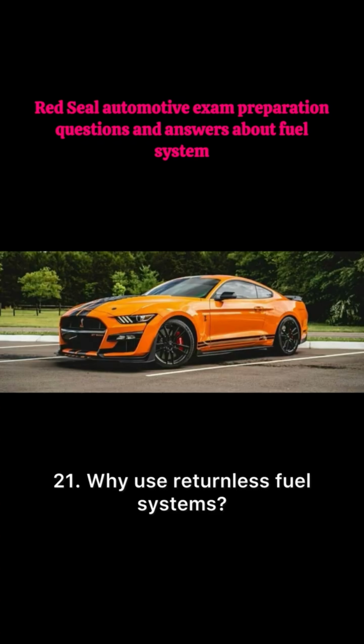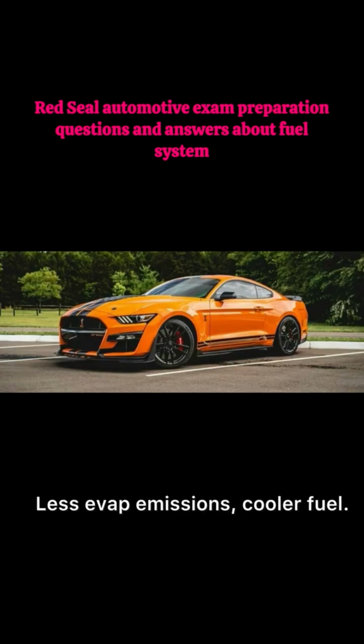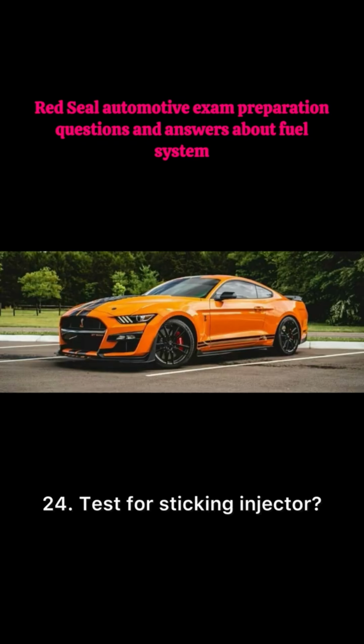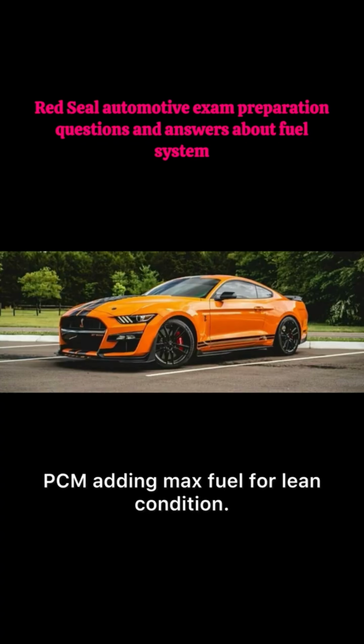21. Why use returnless fuel systems? Less evap emissions, cooler fuel. 22. Saturated injector resistance. 12-17 ohms. 23. Peak and hold injector resistance. 2-4 ohms. 24. Test for sticking injector. Injector balance test. 25. Fuel trim plus 25% means PCM adding max fuel for lean condition.